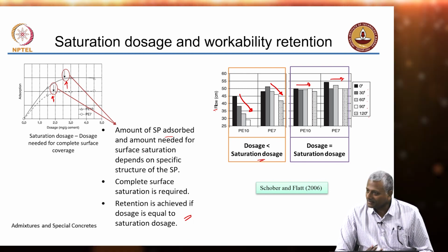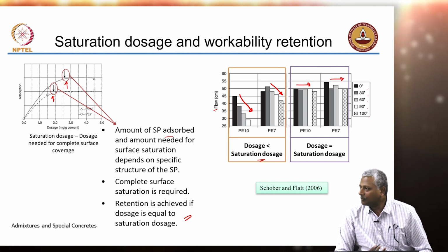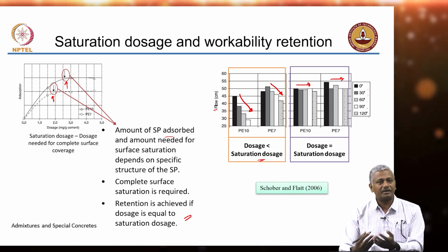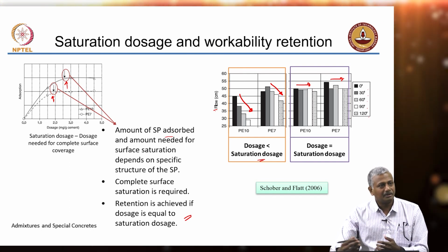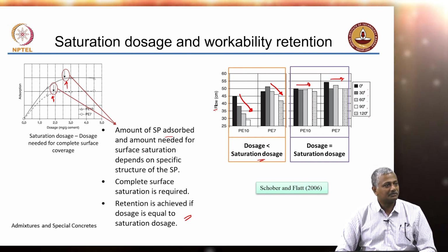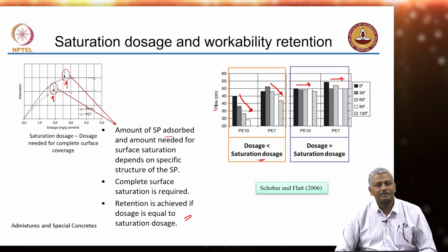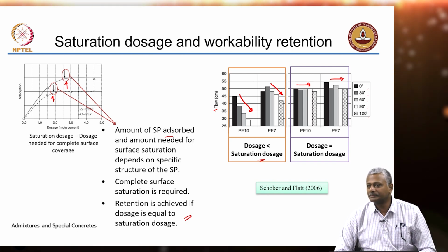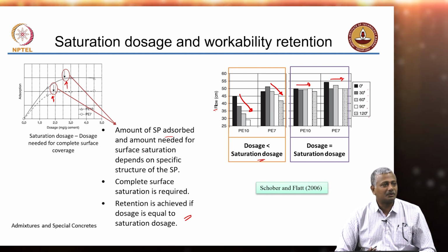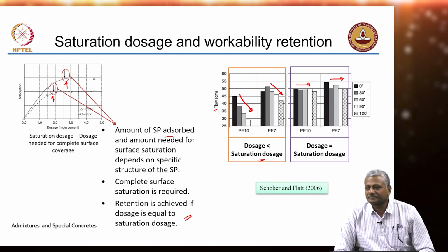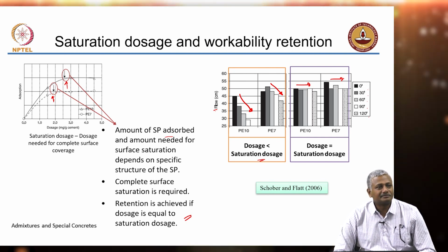Now, what is happening there? Obviously, it is a case of adding water. The concrete was not designed for the required initial workability or retention of workability. So, to make up for lost time and to ensure that the project went ahead, they added water, and ultimately got a strength of only 10 to 15. Now, what do you do? The structure is already up. What do you do now?